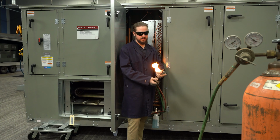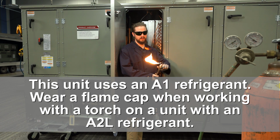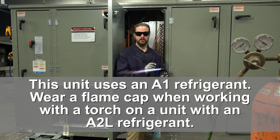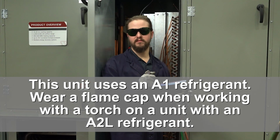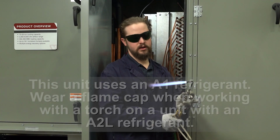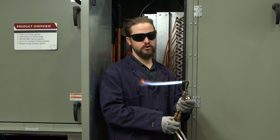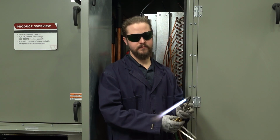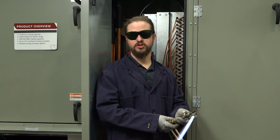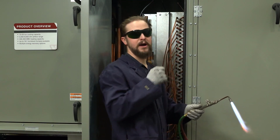All right, let's get my torch lit. So what we're looking for here is a balanced flame. Ideally, you want your flame length as short as possible, just considering the tight quarters that we're in. However, as I turn my torch up and get that shorter flame, I'll end up with a flame that's actually too hot for the pipe sizes here.